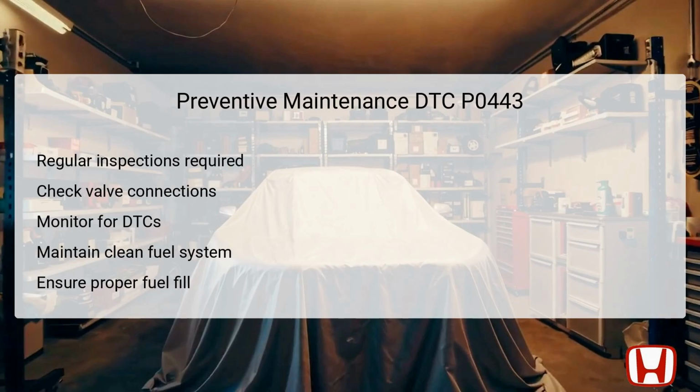To prevent future occurrences of DTC P0443, implementing regular preventive maintenance is crucial for ensuring the integrity of the EVAP system. Regular inspections of the EVAP Canister Purge valve and its connections can significantly minimize the risk of malfunction caused by wear and tear or corrosion.